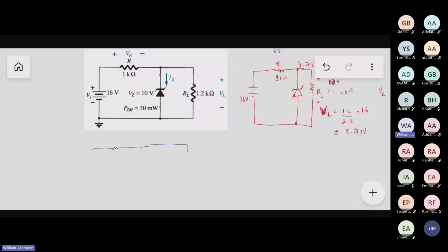Just take it off. Don't leave it there. Because when it starts working, until the voltage reaches the minimum that it needs, the Zener diode is barely there. It's not there. So just take it off. Then the voltage keeps ramping up.